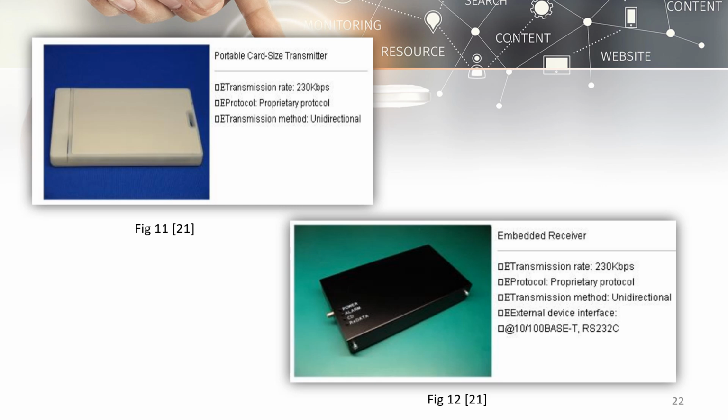per second. In some physical applications including entry control and ticket gate systems, with the transmitter carried in a jacket, vest pocket or trouser pocket transmitting an ID, we achieve communication with a packet error rate of less than 10 raised to minus 3. The next is an embedded receiver which comes along with it.